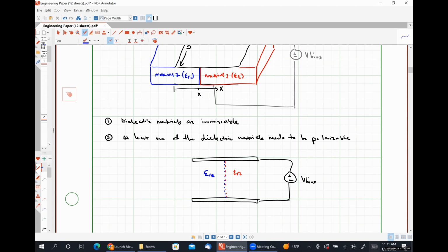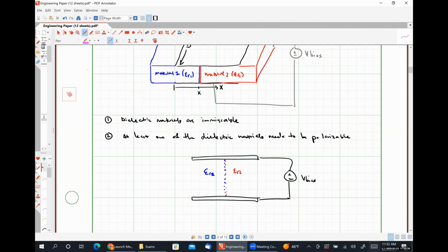Because we have a capacitor, we know that we have an electric field E like so, that's oriented down, so from the positive polarity electrode to the negative polarity electrode. Because our capacitor is not infinitely long, we're also going to have a fringe field at the edges. Okay. So in previous examples, we've ignored our fringing fields, but here it's actually the fringing fields that are doing all of the work. Okay.